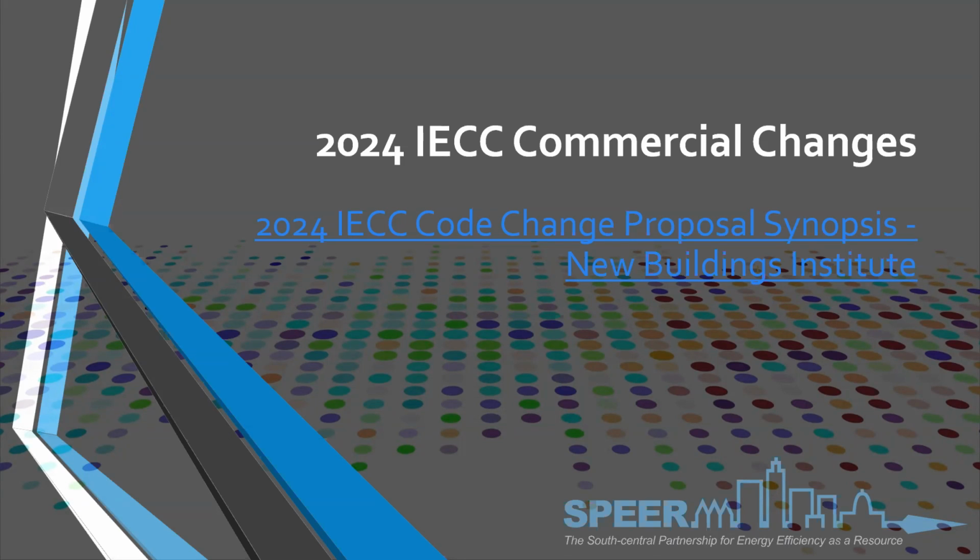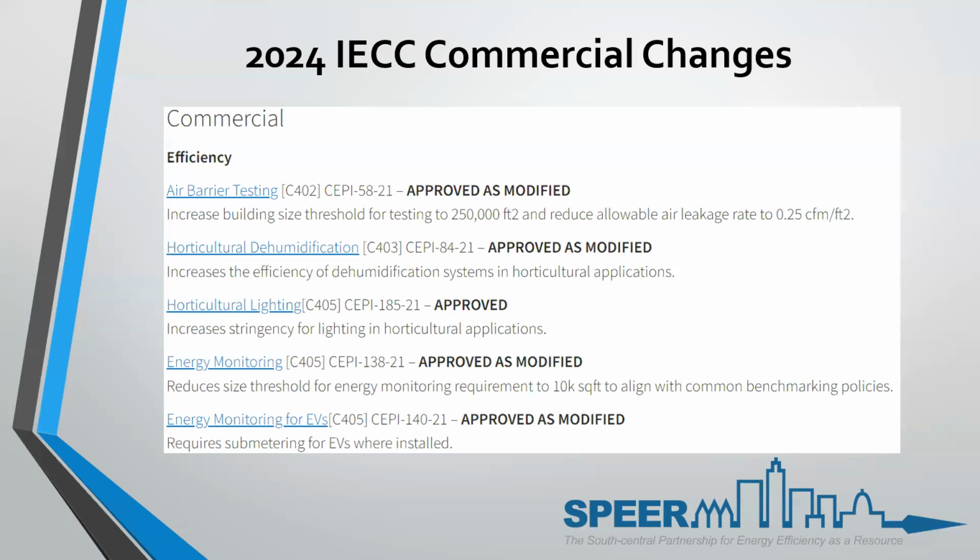They are just posting the ones that either have made it, or made it by modification, or some that have actually been withdrawn. This is not a list of all of them. It's just a list of the ones I put up that I thought were pretty surprising. So you've got air barrier testing. It increases the building size threshold for testing to 250,000 square feet and reduces the allowable air leakage to 0.25 CFM per square foot. That's if it's being air tested. I think there's still going to be that allowance that you could do testing, or you can also do a visual inspection.